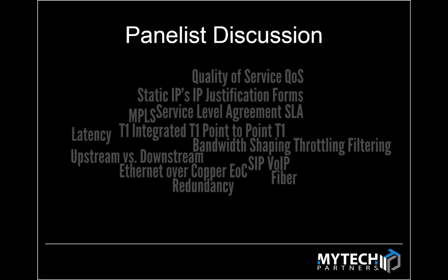Yeah, just to add to that, this is Jim with Frontier. Here in the metro area, probably 85% of our metro Ethernet customers, where we're delivering anywhere from 5 meg to 30 or 40 meg in some cases, are delivered over copper today. It's those rare exceptions where someone absolutely has to have fiber, for example a 100 meg or gigabit connection, where they need fiber to support that kind of bandwidth.